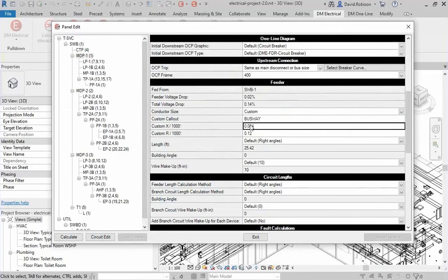Another example, say you want to do multiple parallel runs of conductors, but you want to put them all in the same conduit. We had a customer who asked for that within the last month, actually. So our software doesn't have a way to do that. If you're doing parallel runs, we assume they're in separate conduits. So now you could just do a custom call out for that specific circumstance, do the larger conduit, do the multiple wires, and then figure out the impedance values as well.